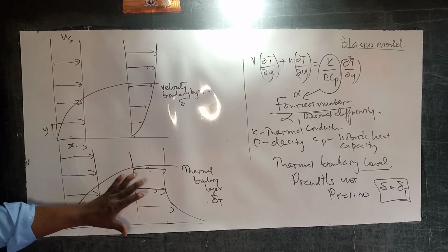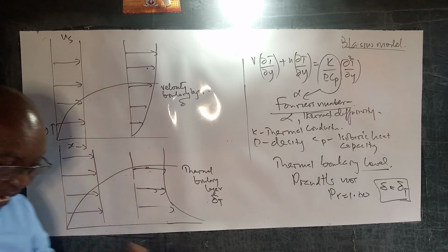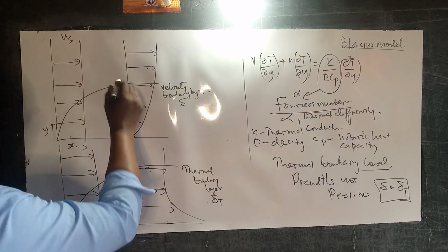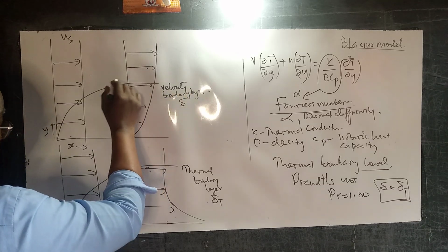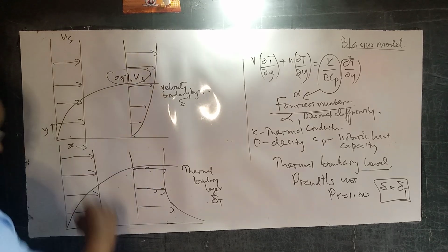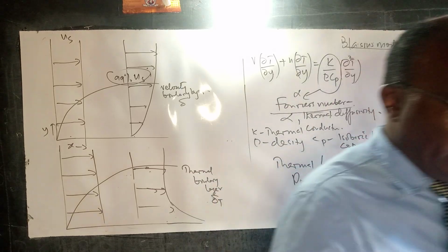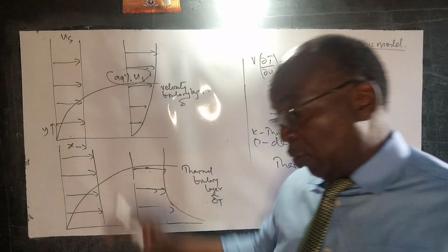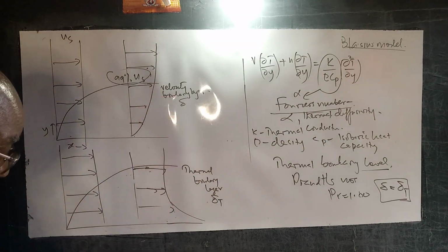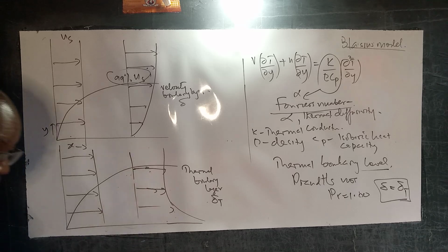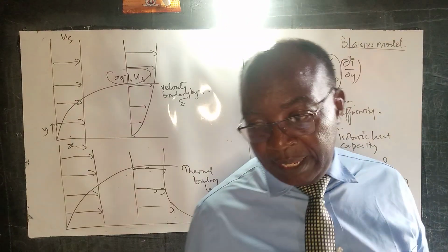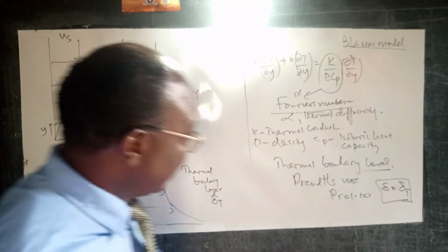Like we mentioned, the boundary layer represents those cases where the velocity is less than 99% of the upstream velocity. It approaches the upstream velocity, but is below 99% of it, what you call the far field velocity. The same applies to the thermal boundary layer in terms of temperatures, in the same manner which we have discussed for the velocity.